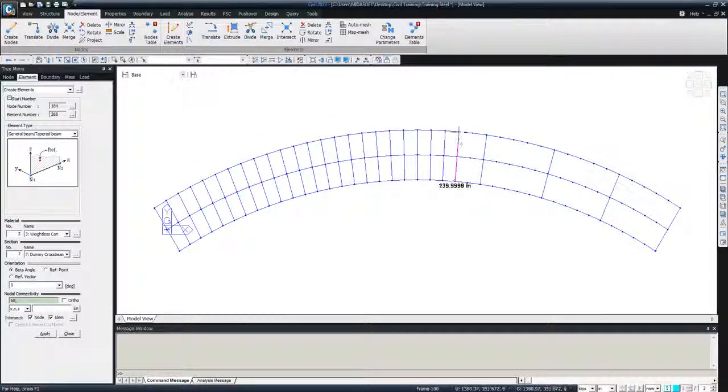Just keep going to finish these. And again, keep in mind to check these nodes and elements, because each time I do that, this is connecting the two exterior girders with the middle girder as well. Otherwise, if those are off, the first girder and the exterior girder will be connected, but the middle one will be left behind.